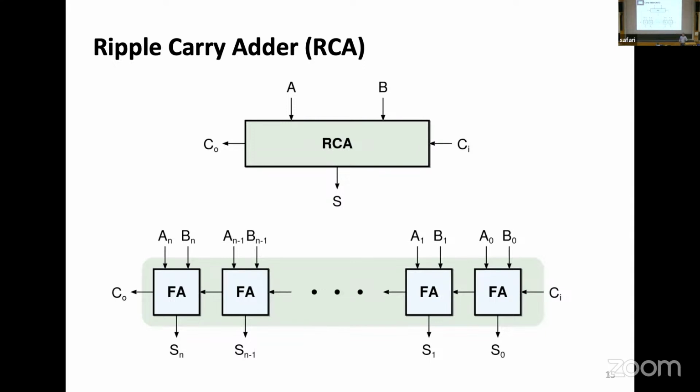First of all, because it's very simple. You define a ripple carry adder of arbitrary bit length like this. You have two vectors, A and B entering. You may have a single bit, a carry in, entering to this adder from the right side. And it will calculate a sum that is equal to the length of the input vectors. And in addition, it will create a carry out in case this addition results in a number that cannot be expressed in the length of S.